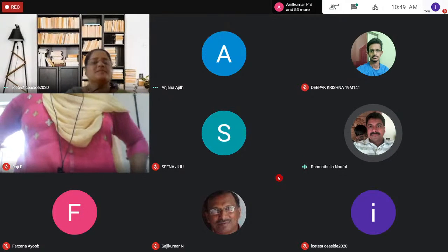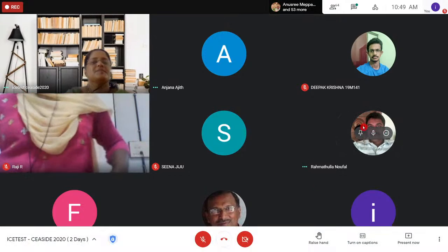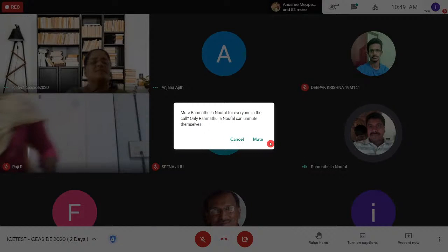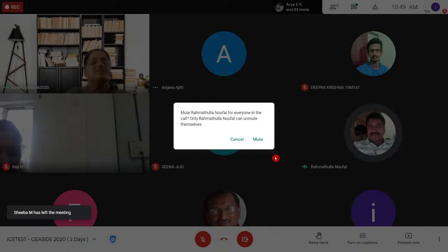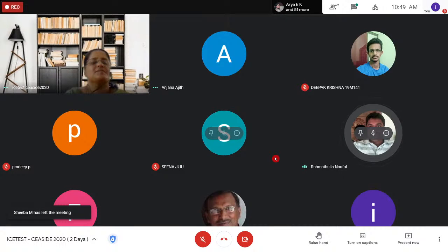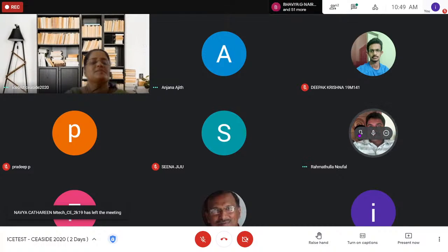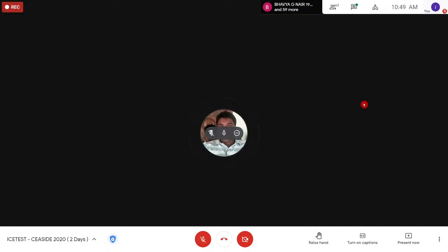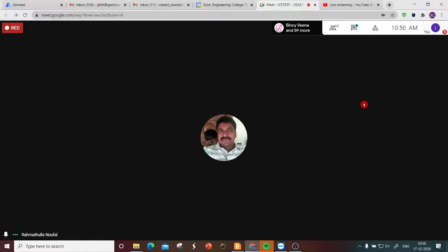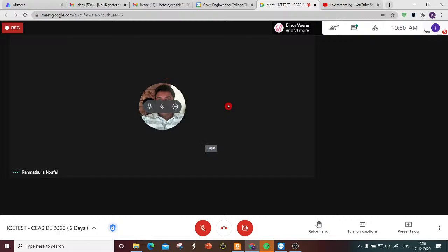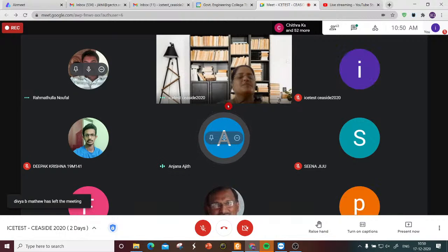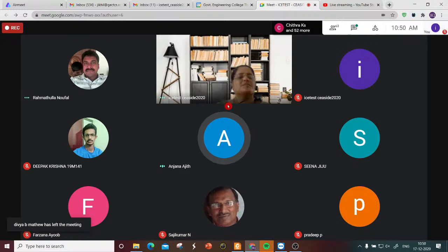The shape of the copper slag is not similar to river sand, and the bonding between the materials depends upon the phi value, the angle of friction. That's why I calculated this phi value, to compare the phi values of river sand with the copper slag, and the values come almost the same. It is only because of the bonding. Bond stress for concrete is found in a different manner, that's why I asked this. No, madam, it is not for concrete. It is just for comparing copper slag with river sand.